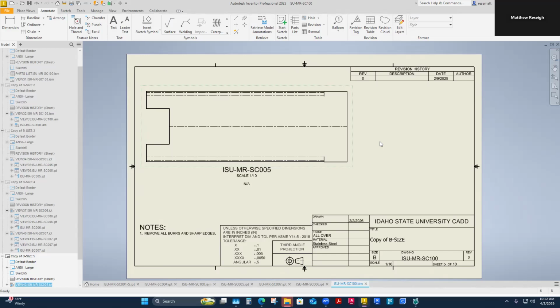And it'll even have a little description that says, see, this is on sheet 12. There's a revision. You go to sheet 12 and you'd see there's a revision history that's been applied to that sheet, and maybe there's something bubbled or ballooned around it with a view label of what was revised. But right out the gate, I only really am going to have one revision history block on that first sheet. But I don't know what sheet that is.